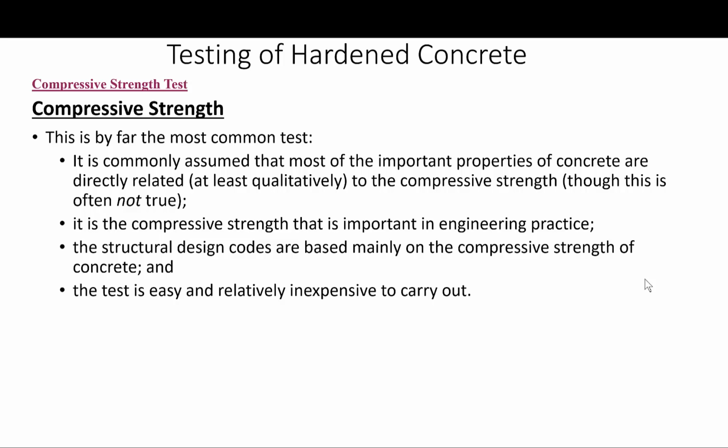By far, the most common test carried out on concrete is the compressive strength test. Okay, there are several reasons for this. First, it is commonly assumed that most of the important properties of concrete are directly related, or at least qualitatively, not necessarily quantitatively, to the compressive strength. Okay, though this is not always true.